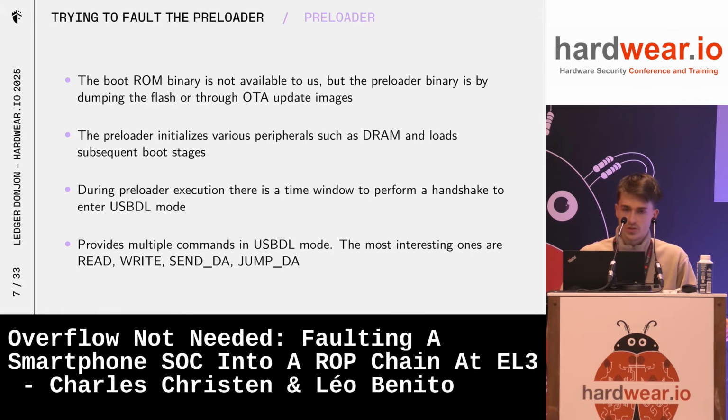And among the commands exposed by the USBDL mode, the most interesting fault targets for us are the read and write commands, which allow reading and writing some dedicated areas, and also the sendDA and jumpDA commands. DA here stands for download agent, which is a binary signed by MediaTek. sendDA allows loading such a binary on the device, and jumpDA allows executing it.